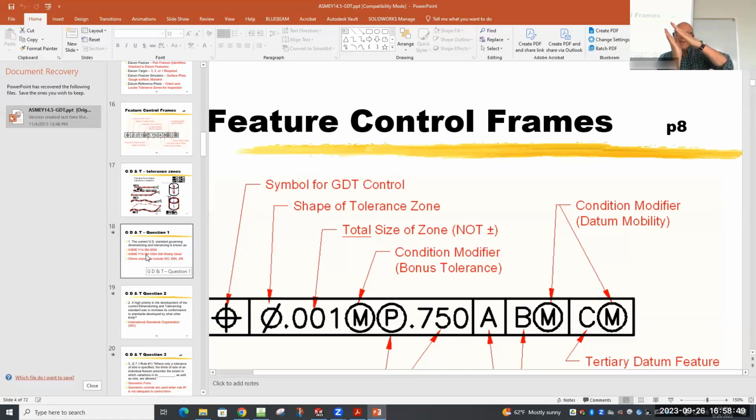Whereas if you say, no, no, no, that surface has to be 30 degrees within that sandwich, the theoretical sandwich is 30 degrees because the tooling you made holds it at 30 degrees. Now you find out by dragging, you do the same thing. You basically set it up so that you now have this at an angle that you can control. You drag it all over the surface. And as long as the surface doesn't extend beyond that sandwich, its tolerance is close enough.